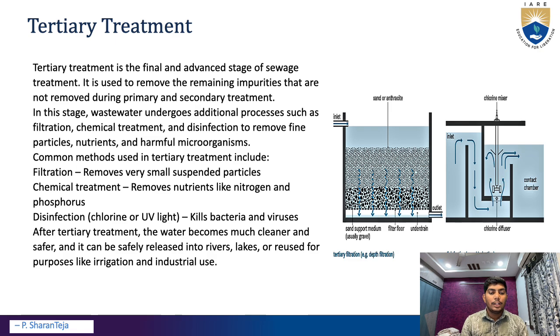In this stage, wastewater undergoes additional processes such as filtration, chemical treatment, and disinfection to remove fine particles, nutrients, and harmful microorganisms. After tertiary treatment, the water becomes much cleaner and safer, and it can be safely released into rivers and lakes and reused for purposes like irrigation and industrial use.